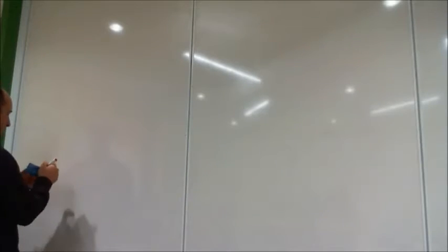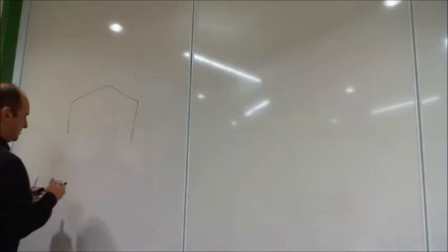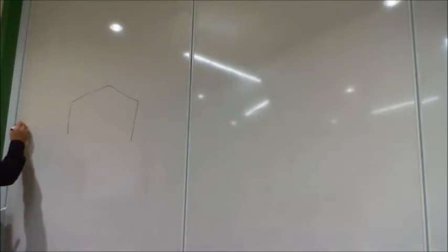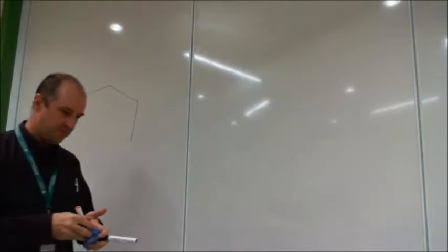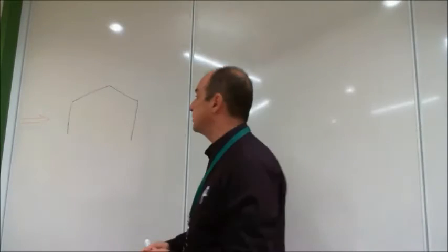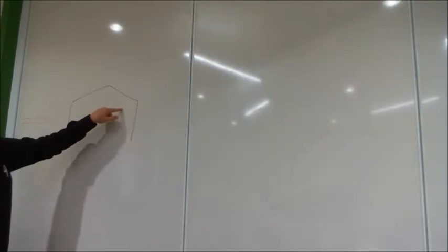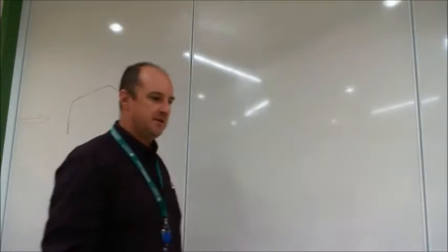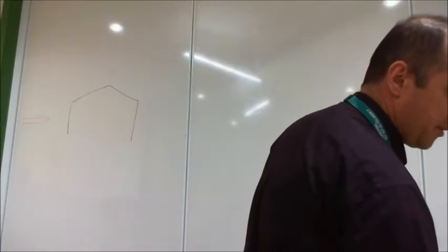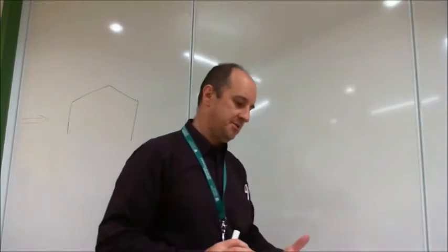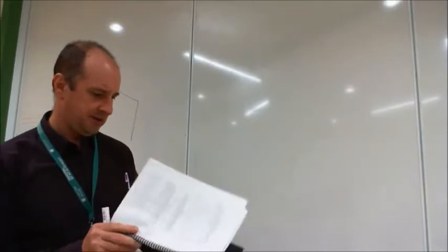All right. So what you do then is, let's get a building. Go a bit smaller. And let's consider the wind from this direction. Okay? The first thing you get is an internal pressure. Depending on the openings, that's going to be inflation or deflation. Now, if you notice in this table for internal pressure, and for a lot of these tables, they give you two values. So, for example, leeward wall.